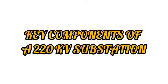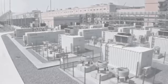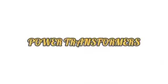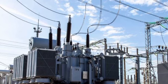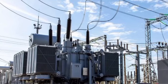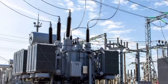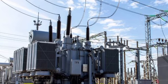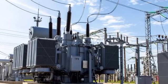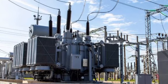Key components of a 220 kV substation. A 220 kV substation includes a variety of high-voltage equipment and support systems. Below is a detailed list of essential components. Power transformers. Voltage rating 220/132 kV, 220/66 kV, 220/33 kV, capacity 100 MVA to 315 MVA, cooling ONAN/ONAF, may include an on-load tap changer, OLTC.